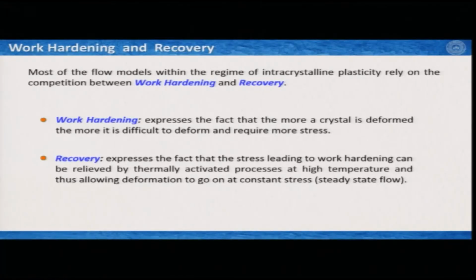Work hardening expresses the fact that the more a crystal is deformed, the more difficult it is to deform and the more stress it requires. That means the system that I am deforming through intracrystalline plasticity requires more and more stress to deform it.